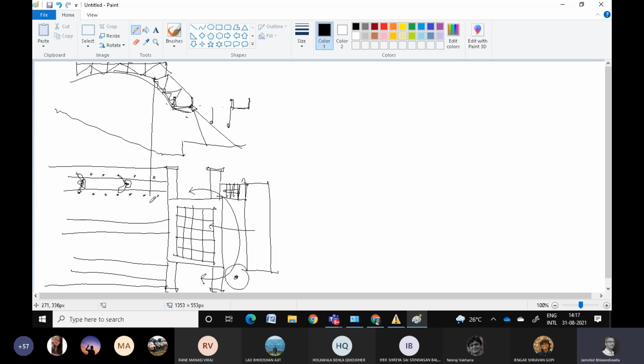If there are stairs, then make sure that your stairs reflect. And naturally, the false ceiling panels that are there will all reflect in the reflected ceiling plan. So in the reflected ceiling plan, you will see a plan such as this that will show the positions of the catwalk, that will show the positions of the panels, whether you would like to have fragmented panels or straight panels that are there.